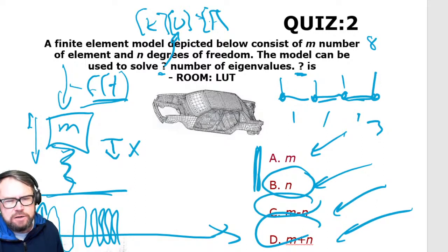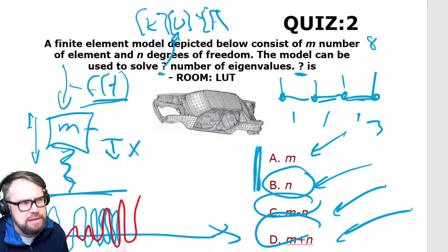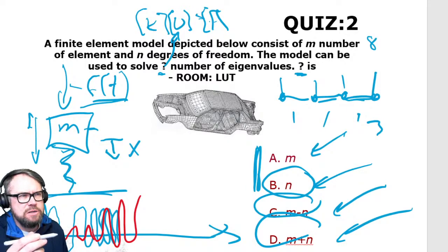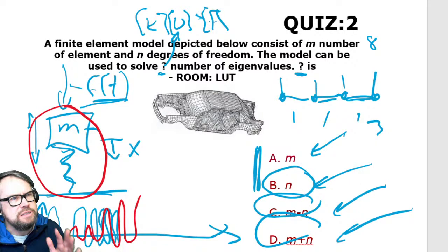And what will happen to this structure is that this mass will follow the motion. Let me change the color to make this more clear. It follows the behavior in a certain way. But once it hits the natural frequency of the structure, then this response becomes unnaturally high. This is called the resonance condition, and the resonance condition is a feature of the structure, a combination of mass and stiffness. When that combination is in a certain range, the structure can have a resonance. Particularly if the loading is at the same frequency, the structure is in resonance, and then the response will be very high.